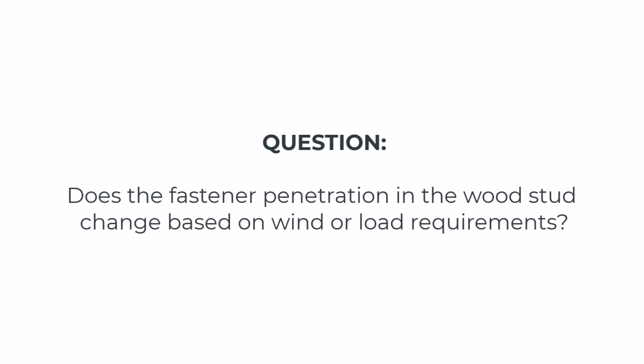Now, their schedules that they've been through testing both ways for seismic capacity would account for it, and the strength they assign should account for those different orientations of the panel. But all other things equal, if there's no change in fastening, having the foam to the interior should weaken the shear capacity.